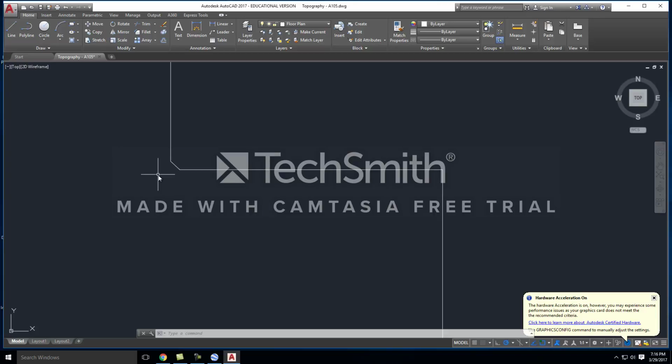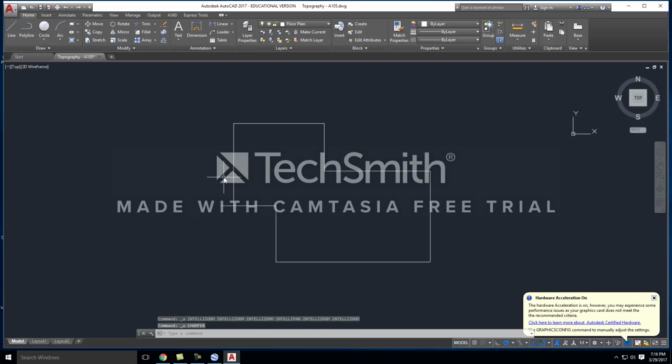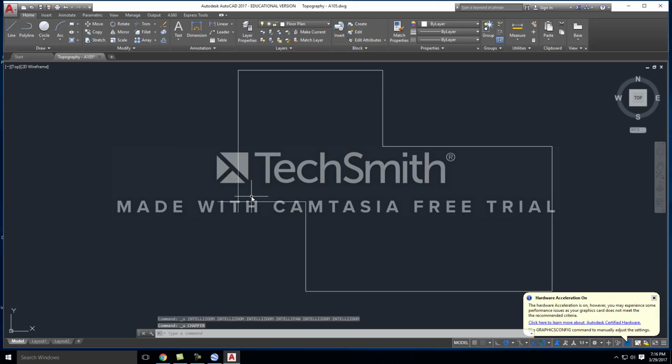Okay, so you might have a scenario kind of like this. All right, so you do CHA for chamfer, enter. Then I'm going to hit D for distance. It's going to ask you to specify 2 different chamfer distances. I typically do the same distance for both. That will give you a nice even connection like this. You can specify multiple distances if you want, but you're not going to get that even look like you see right here. Okay, you might get something that looks like this.